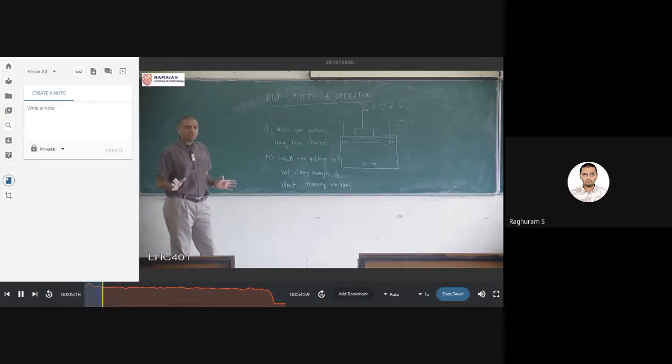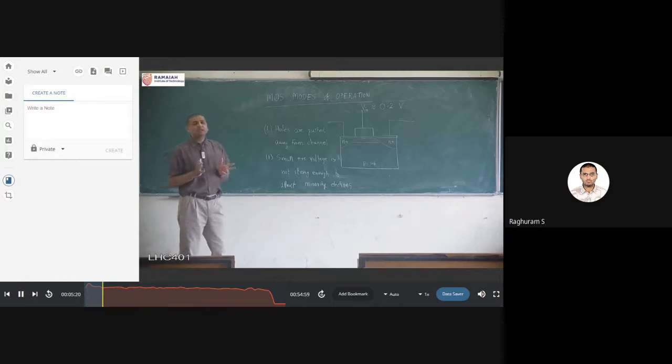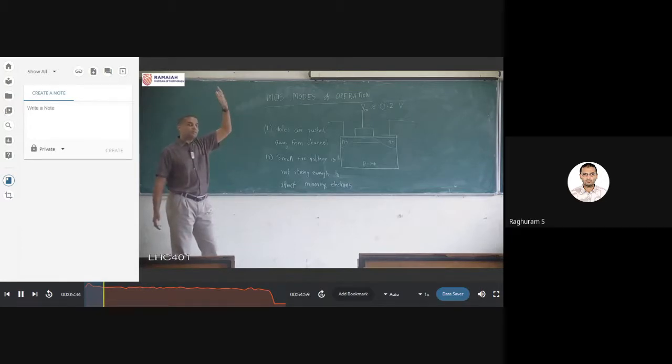electrons is not zero. Concentration of electrons is very small. It is around 10 power 17 per centimeter cube. It's a very small number, because in silicon, for example, the number of atoms is 10 power 23 per centimeter cube. So 10 power 17 divided by 10 power 23 is 10 power minus 6. You have nano, you have pico, then there's femto, and I think 10 power minus 18 is atto. Compared to silicon, it is very small.